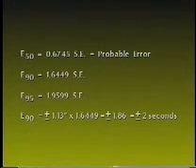As a surveyor, you probably wouldn't want to tell your client that you're only 68.3% certain about the results of your measurements. A 90% or 95% level of confidence would be much better. You can determine different levels of confidence by multiplying the standard deviation by a constant that, again, has been determined by the laws of probability. Shown here are the 3 most common levels of confidence that a surveyor should be familiar with.